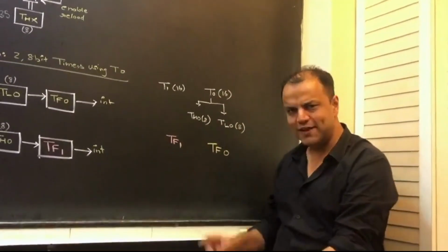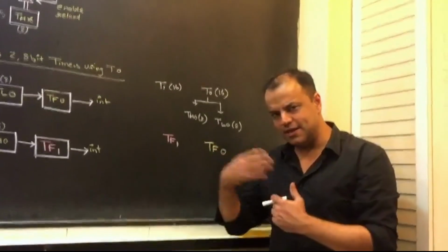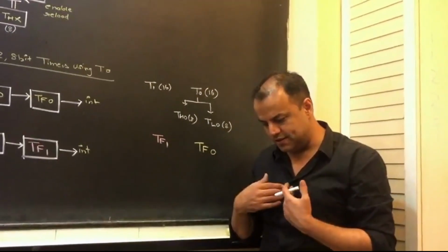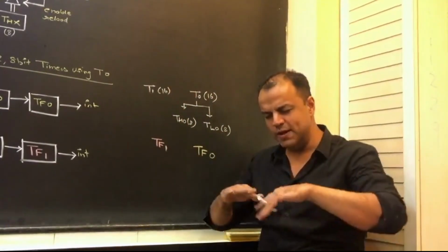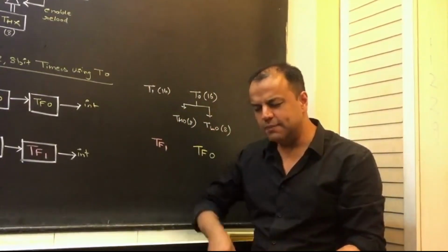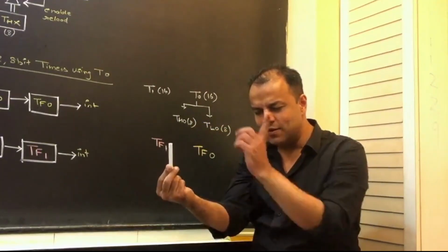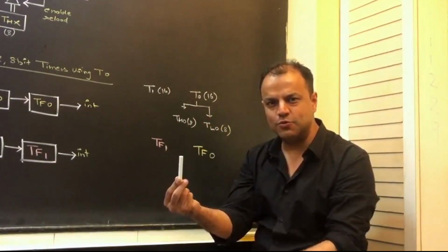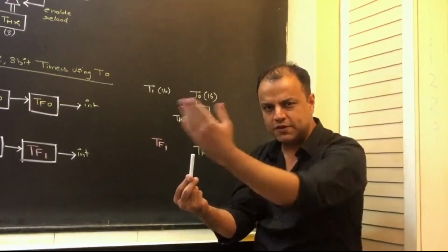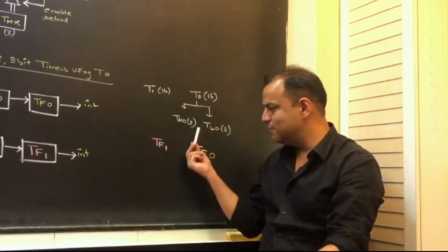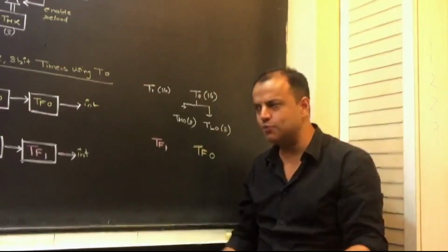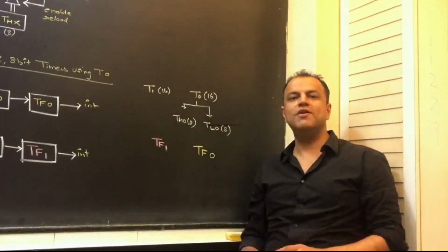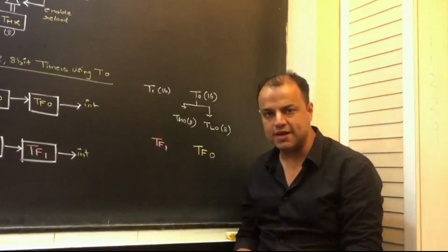Are these overflow flags important? Yes, they are the connection between the timer and the processor. Timer is counting, processor in its own world. When the timer overflows, it makes the overflow flag 1, which informs the processor that the timer has overflown. So the link between the timer and the processor is the overflow flag. They don't share one flag, they have independent flags, which means both can independently overflow. So what you have so far is a beautiful system with two 16-bit timers.